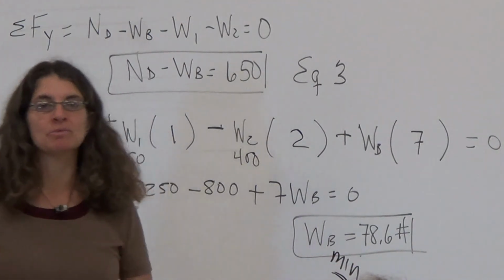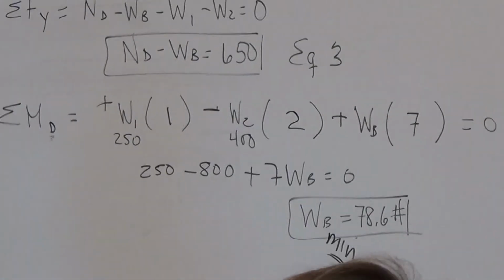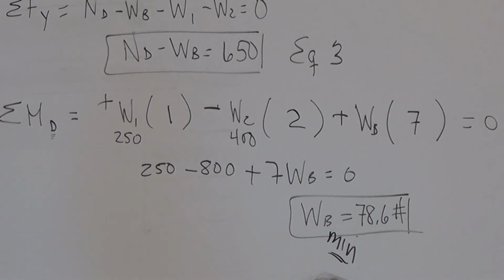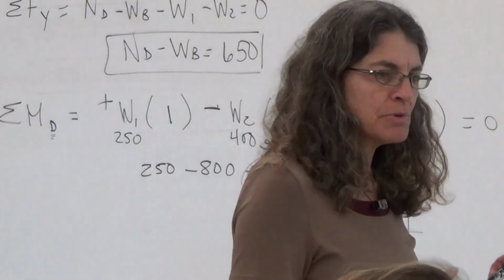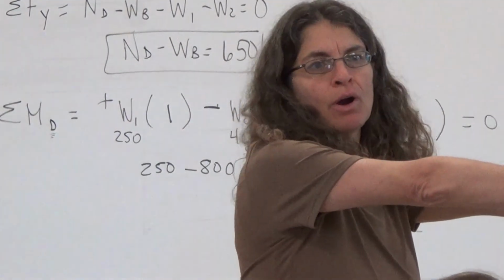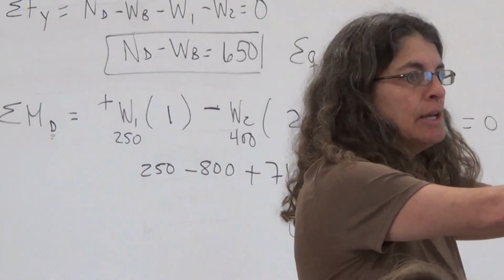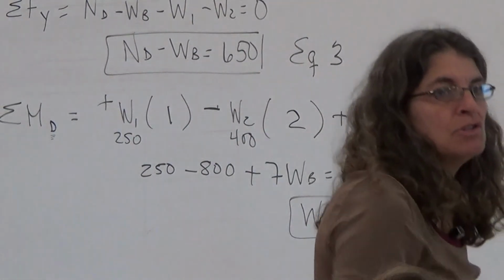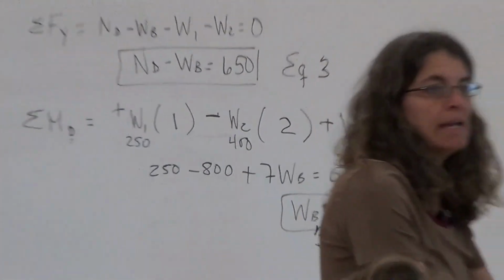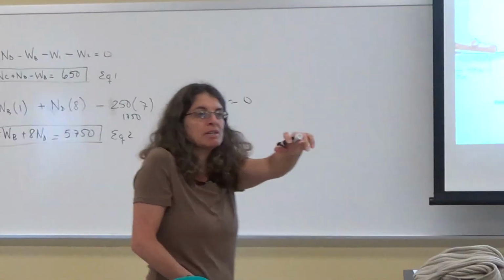You did a friction problem already, without friction. There are a few problems where somebody's pushing a refrigerator or a box or crate, and depending on where they push it, it could either tip over, or if they push it low enough, it's going to slide. So you want to analyze it for both sliding and tipping, so you do rotational analysis as well as translational.